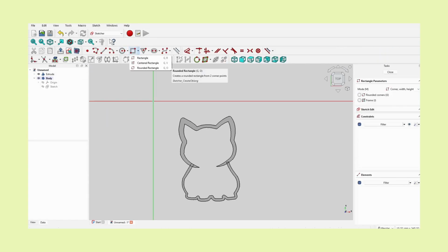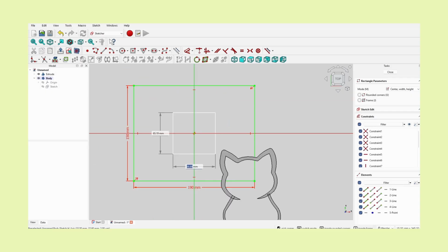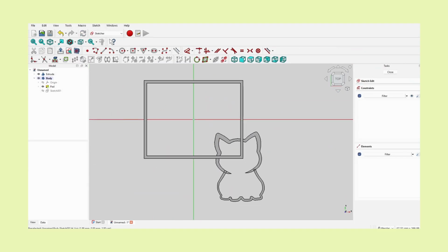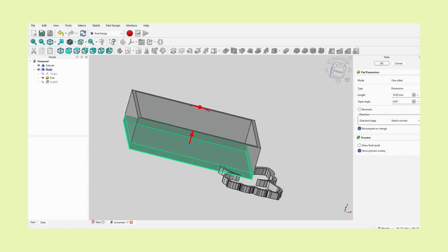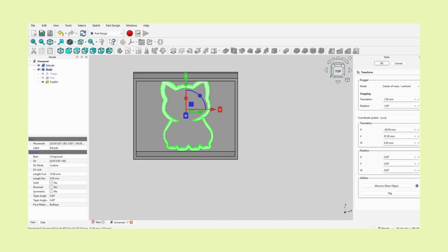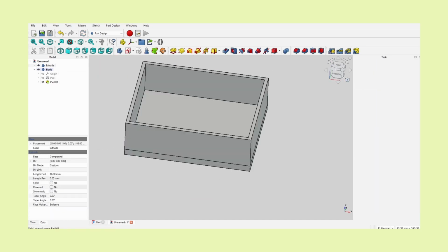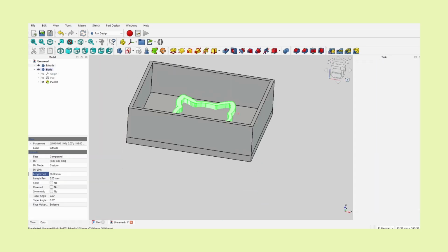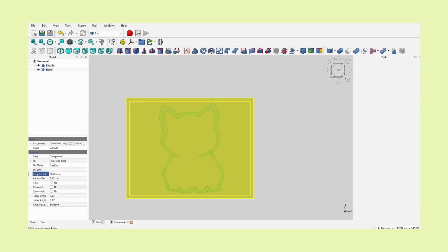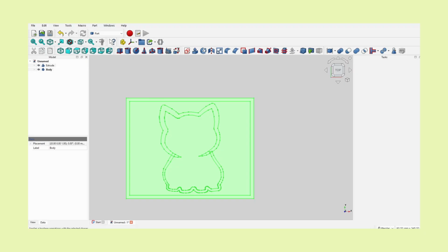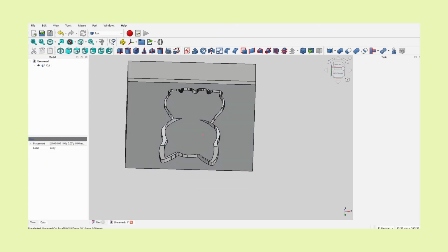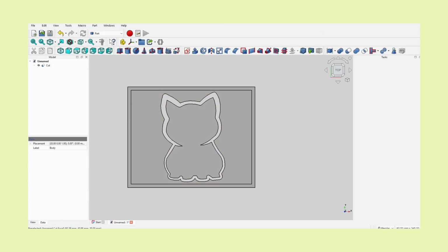In order to create a decorative imprint or a stencil, you'll need to conduct a Boolean operation. Here, I'm just going to model a quick box as an example. You'll want to select your extrusion and then place it over the plane where you want to conduct your Boolean operation. Then, you'll need to select your box and then select your extrusion. With both selected, choose the option on the top that looks like two balls. This will complete your cut.